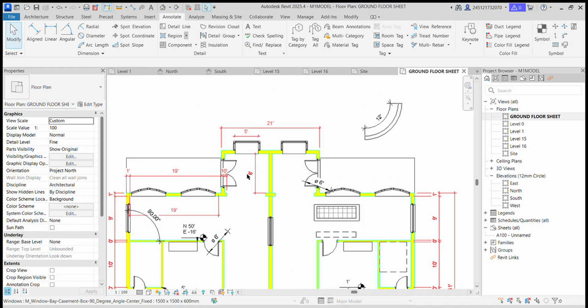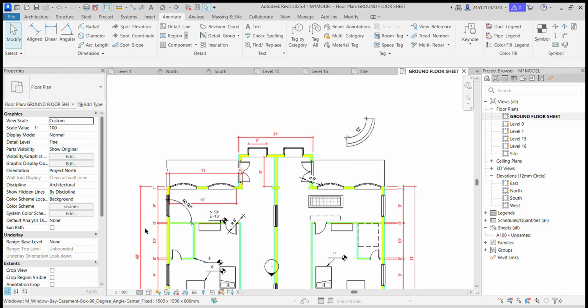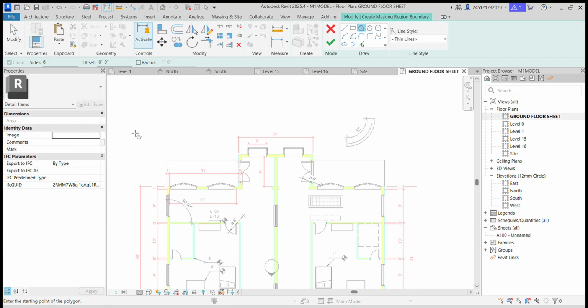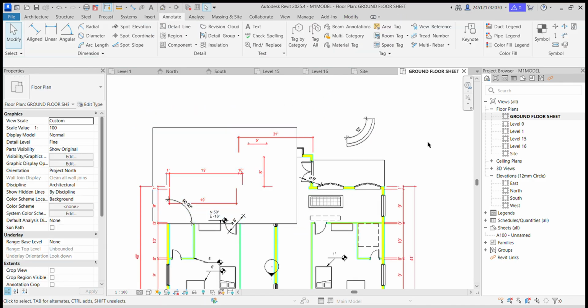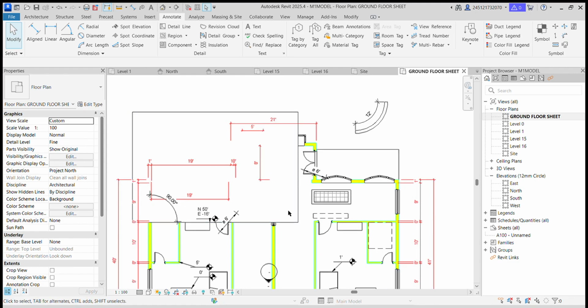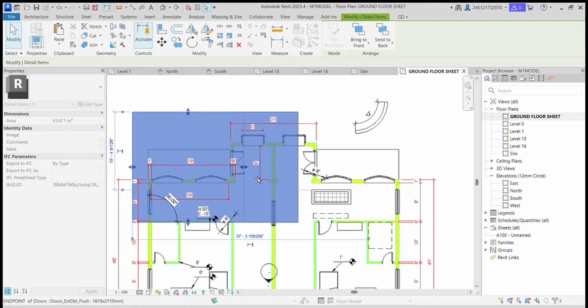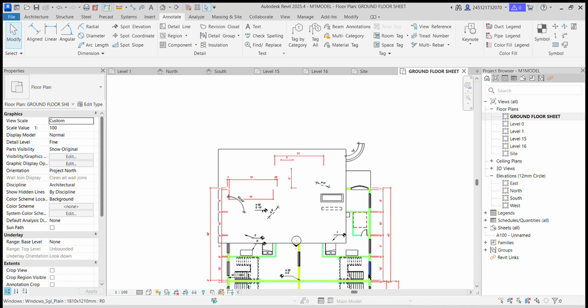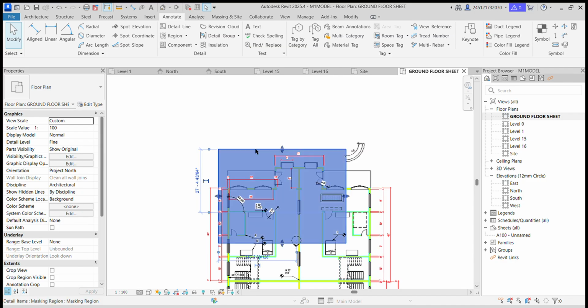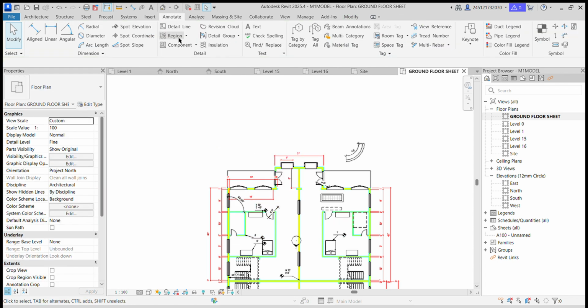Listen, if I want to hide some detail from this particular sheet, because I want to hand it out to the client, but I don't want them to check the drawing. Okay, in that case, if you didn't work here properly, you can simply hide it by using a mask. Okay, this is a rectangle. You can draw it now. It will be masked. Okay, finish it. Now you can see, you can just hide the model. So wipeout is nothing but it will hide the selected objects. While printing, it won't show. Okay. So note down, this is a masked element.